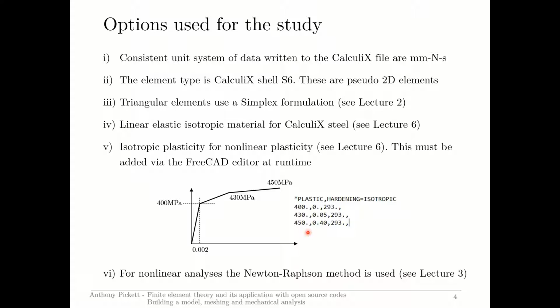It has this curve that I'm showing there, defined by a number of points, by 3 points shown here. So that's this point, and this point. And each point is defined by the yield stress, or the stress, and the plastic strain. Plastic strain occurs from this point onwards, and this is the elastic strain. You get this elastic strain from the modulus of the material, 210 gigapascals, and the yield stress. So you can see here the plastic strain values.